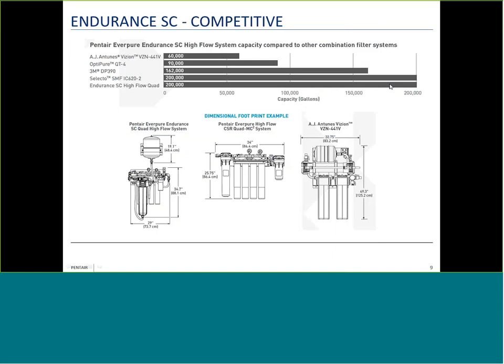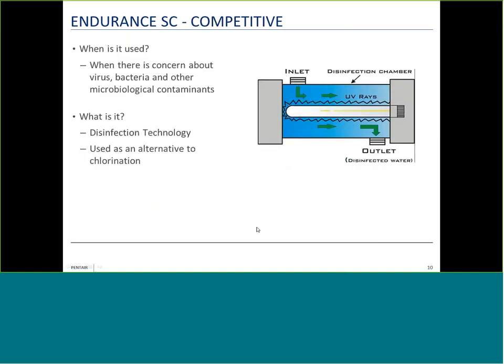And it is used as an alternative to chlorination, where chlorination may be difficult or not very friendly to a back-of-house environment. It is also typically used post-filtration because the organisms it's designed to kill, the viruses, may be able to hide behind turbidity particles or dirt particles in the water, just the way you can hide behind the shadow of something else if you're smaller than it.